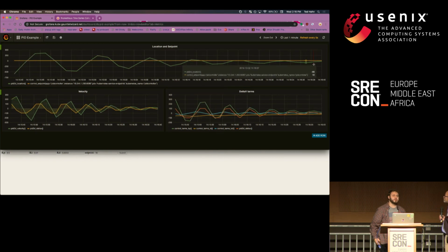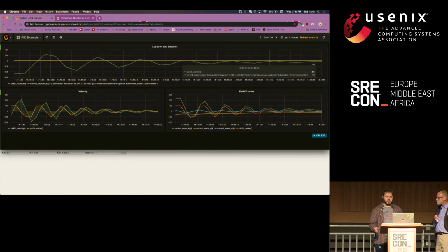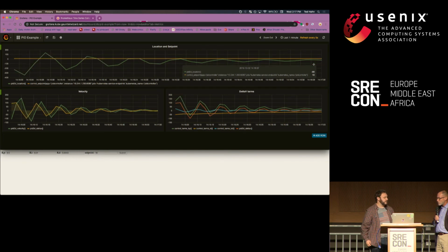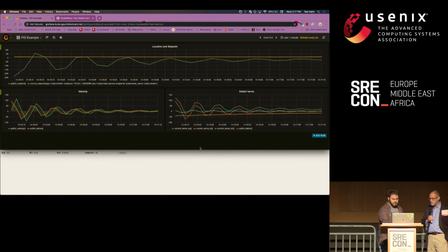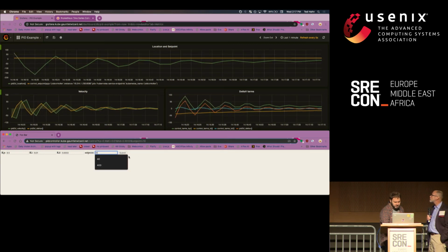Given enough time, a PID controller will get to an arbitrarily small error. However, it will never actually reach 0. You will always see it continue to oscillate a little bit above and a little bit below. In most places that is nothing compared to the actual error from the measurement of the system and from the change in your set point. Your set point will change more often than you can pull the error out of the system. So having converged mostly, let's set this set point up to just another value.